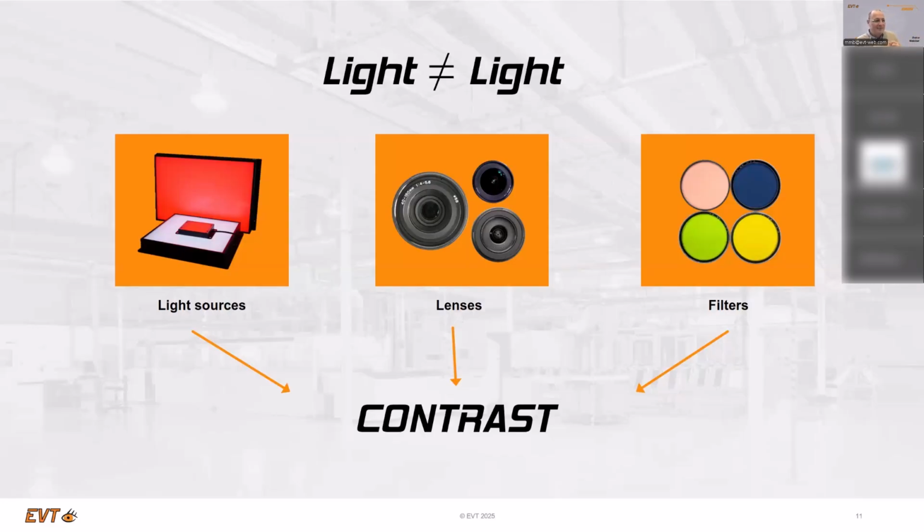That means the light which goes through the lens can only distinguish 5 megapixel. It doesn't help you that you have 20 megapixel, because of the lens you can only distinguish 5 megapixel at the end. That's the maximal frequency which the lens transfers to the sensor. So even if you have a high resolution sensor and a perfect light, if you use the wrong lens, the accuracy you want to reach, you can't reach, because simply it's the wrong lens.